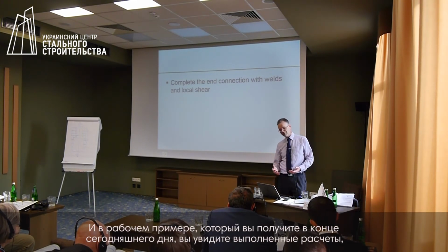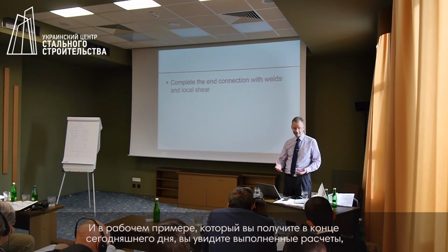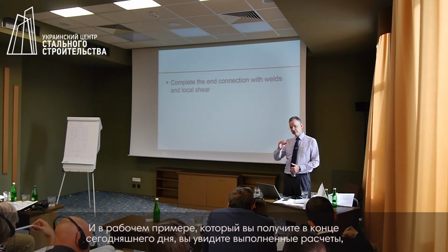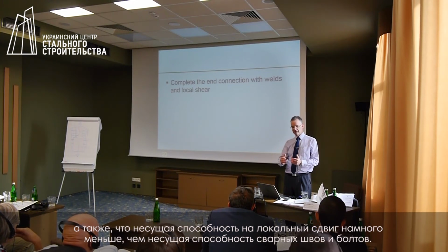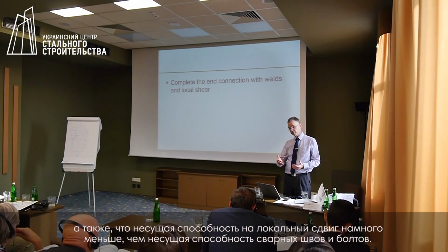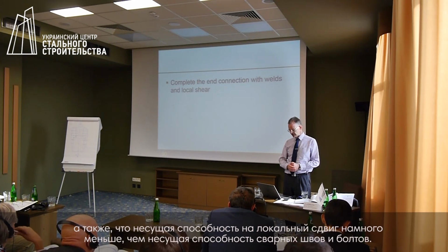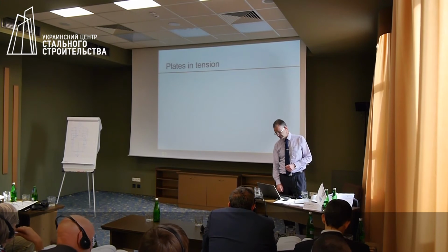So in the worked example that you will get at the end of today, you will see the calculation and you will see that the local shear resistance is much lower than the bolt resistance, much lower than the bearing resistance, much lower than the weld resistance.